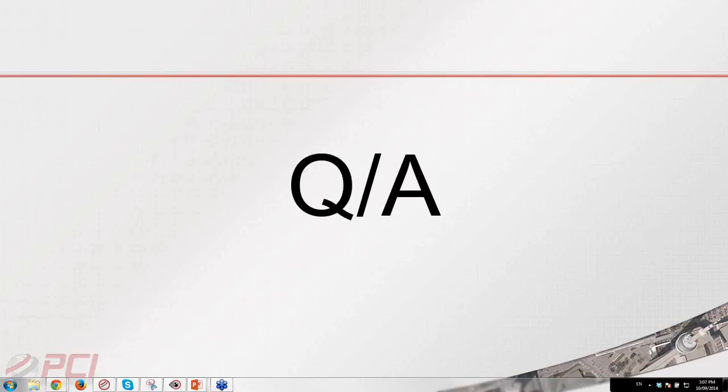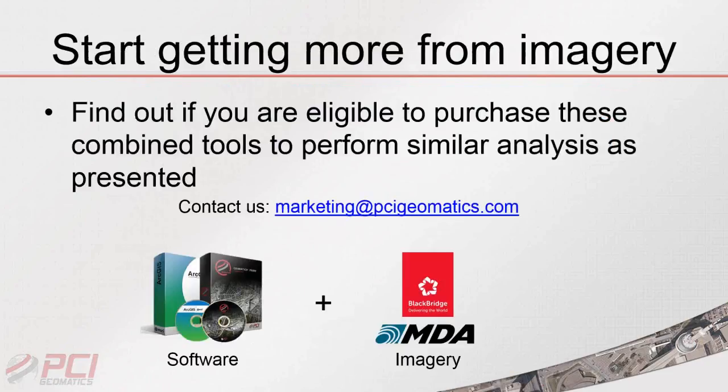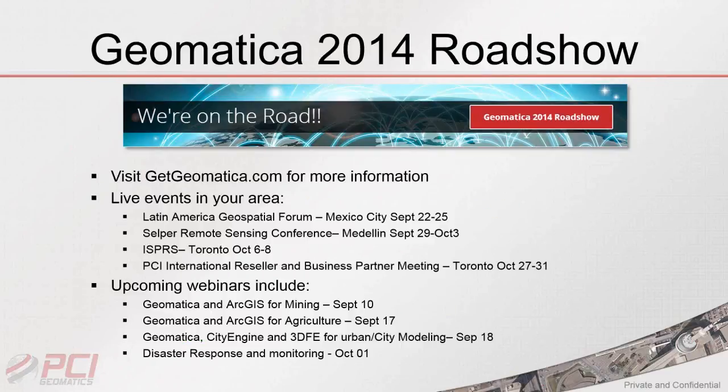Absolutely. So basically, we work a lot with aerial imagery as well. I've worked with DEMs around 30 centimeters, where the imagery that was used to extract those DEMs was 10 centimeters. These very high resolution photos, ortho photos and DEMs can be quite nice to extract certain types of less complex buildings and surface features.